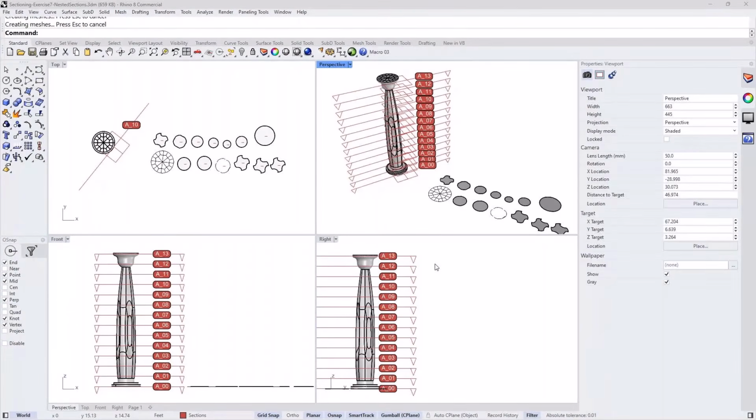Another way to get it registered is if you extract the clipping drawing of that C00, it automatically registers it. After that point, if you array it, it's going to give you unique labeling as well, but you have to use it within the application to tell it that it's a section. That might be improved to be automatic as well, but it's a legacy command. You can open a file that has a clipping plane already created from V6 or something, so it has no knowledge of it to be part of the sectioning suite.